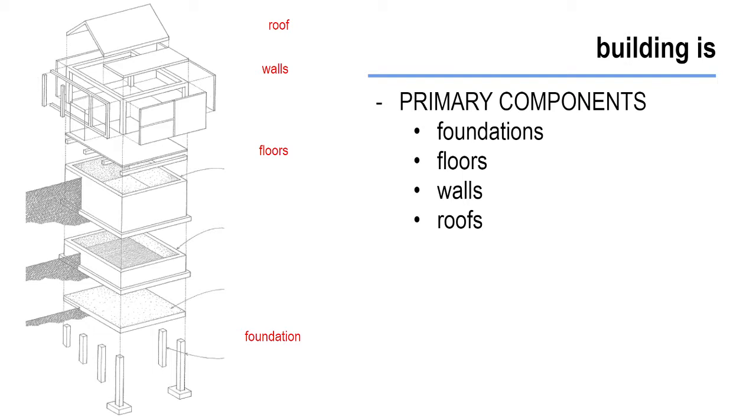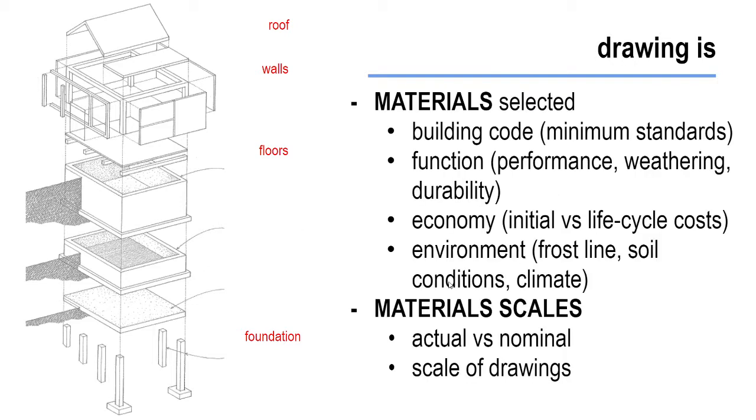So in our small building practice, our roof really isn't an ideal roof, because as the water comes down the slope onto that west wall, it would just fall down that side. It's one of the reasons why we have to have that gutter there on the west wall, because otherwise that side of the building would get completely ruined through water damage.